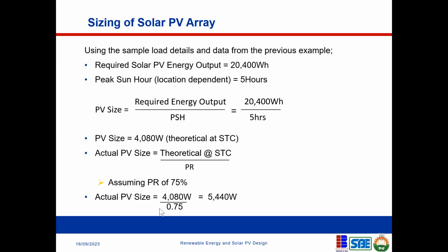So the 18 now, this is the total amount of PV power that we need to install. If we install this amount of PV power and the sun shines on this PV panel for 5 hours, it will produce this amount of energy, assuming it's performing at 25% less of its actual capacity. It will produce this amount of energy.